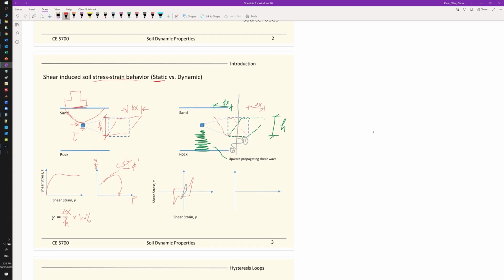So this is the stress path for static loading here, and for cyclic loading, again the same p-q plot, and now this will go back and forth. So this could be your first cycles, and then you keep loading it. And realize this is the mean effective stress, right? The p is equal to 1/3 of sigma V plus 2 times the horizontal stress.